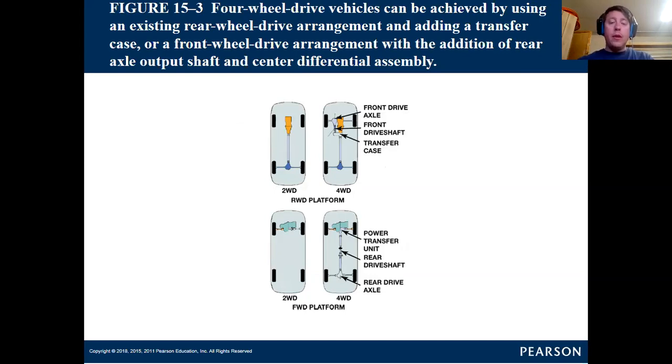They don't necessarily have to be just like your average pickup truck where the rear axle is normally the axle engaged and we lock the front axle in order to achieve four-wheel drive. You can have power transfer to the front wheels most of the time and then drive power to the rear wheels in order to achieve four-wheel drive.